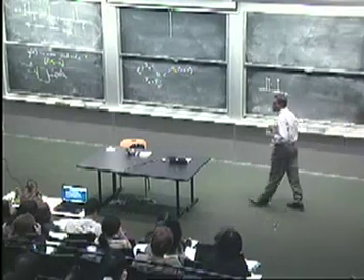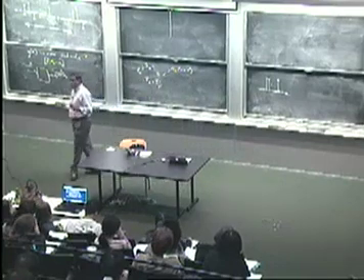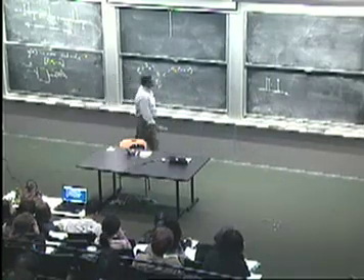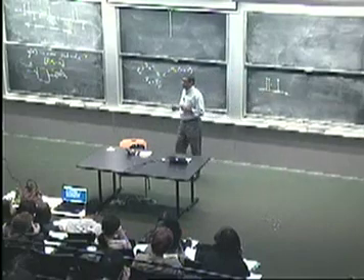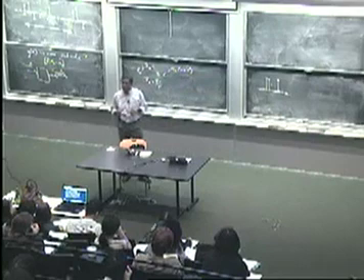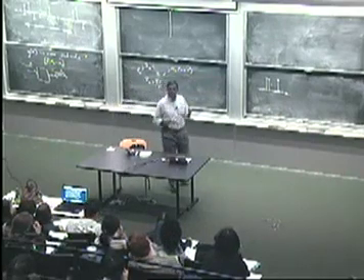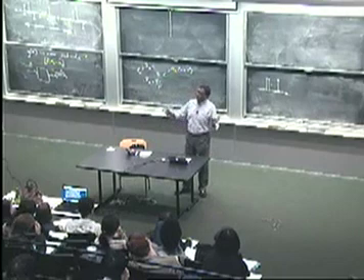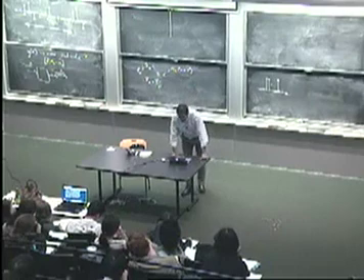Okay, so this case doesn't quite satisfy that band-limited condition. If you shaped your pulse a little bit more carefully, for instance, if you had more rounded edges, then you can pull in the frequency content, and you might do a better approximation to keeping the replicas separate. Or you might use a higher carrier frequency. That'll pull them apart and have less interference. But it's certainly an issue that you need to think about.